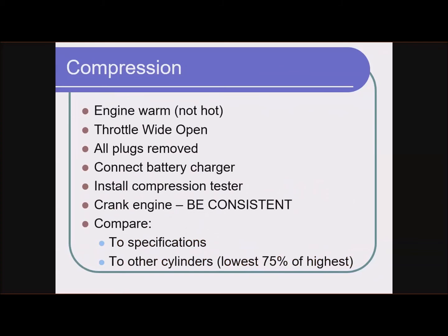We want the throttle wide open. Now, this used to be a really easy thing to do, but unfortunately, it's not necessarily a really easy thing to do anymore. When throttles were operated by cables or linkage, we could just open the throttle with our hands while this test was going on, or just step on the accelerator pedal while the test is going on.